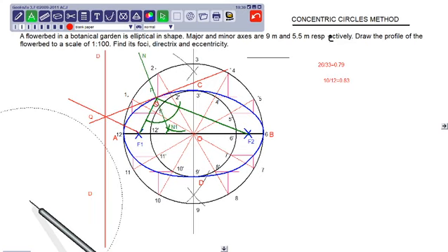How have I found it? I have put the compass at point P and drawn a radius here. Then from these 2 points I have drawn 2 arcs, on any one side, and then the intersecting point of the arcs and the point P I have connected and extended. So this is giving me the normal at point P.